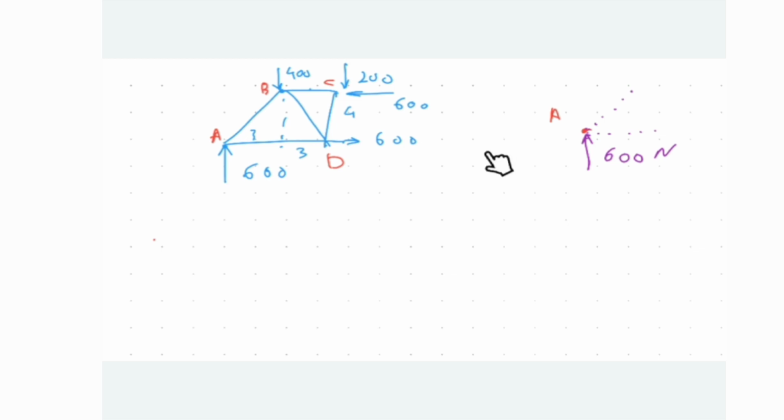The thing is that we can write down the static equilibrium equations for a pin, meaning that I can say sigma Fx is working, sigma Fy is working as well. How about sigma M? Here we have just one point. We can write down sigma M around that point, but this is not working here, meaning that one of the equations is useless.